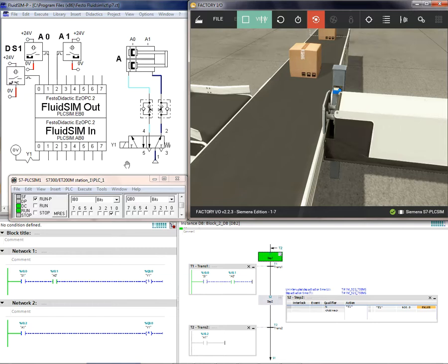Okay, in the next step, when A plus and A1 are connected, A1 is going to reset Q0.0, or reset Y1. And in the graph set language, when this condition turns on, the program jumps from this step to the other step or other transitions.